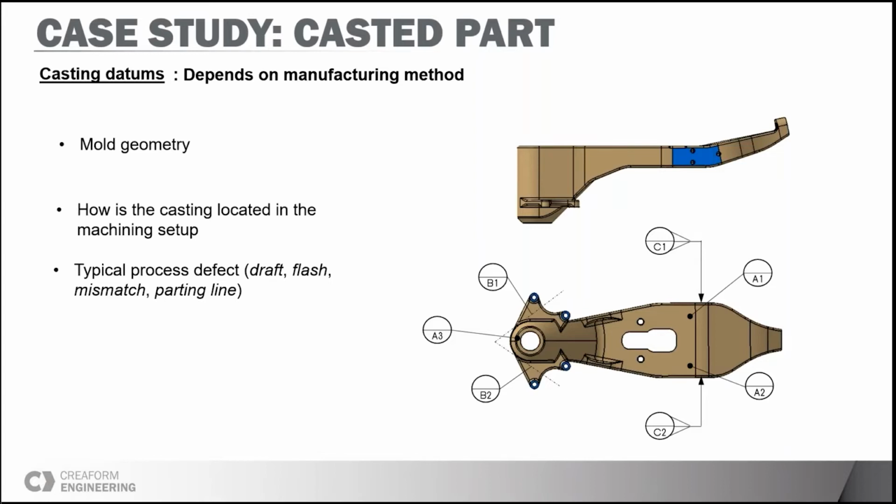You might see on your drawing a tolerance on a profile of a surface, and that would bridge the datum targets on those specific surfaces to the end where you have your datums on your machined surfaces. So that's usually the link between the two.